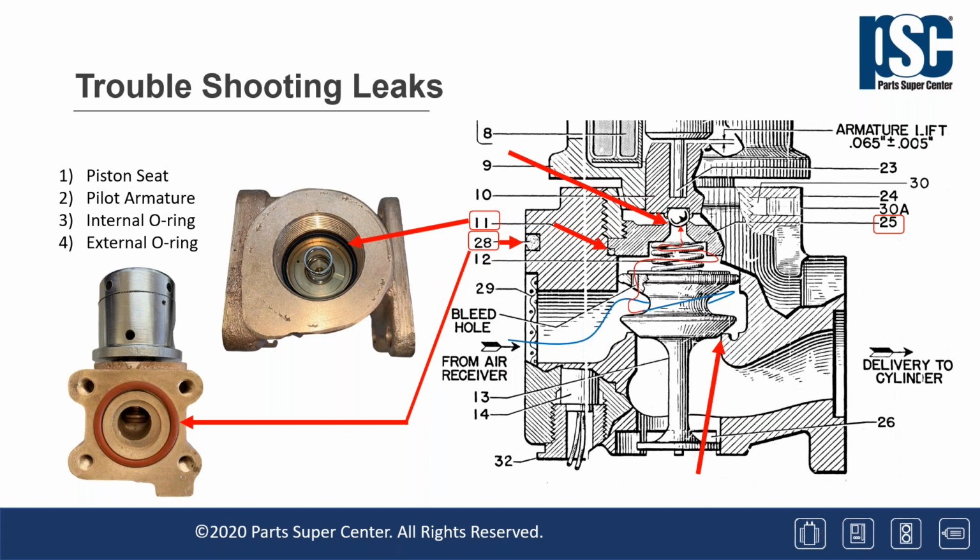So if the external O-ring is leaking, you'll be able to test to detect that leak at the bolted interface using a leak detecting liquid. So you can see in the photograph that there's 4 bolts that attach that flange to the plumbing within the mechanism.